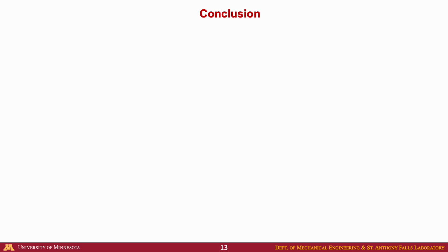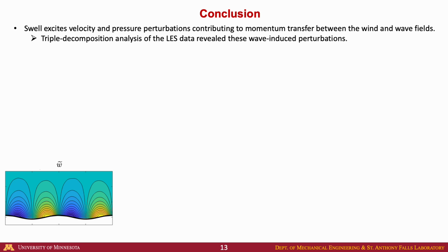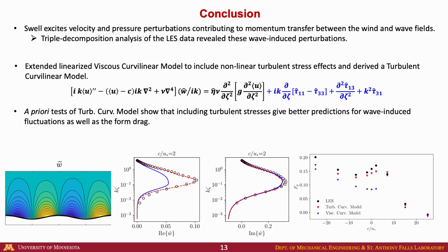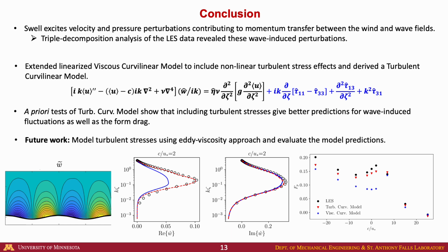In conclusion, we saw that swells excite airflow disturbances, and we were able to visualize and understand its properties through triple decomposition analysis. We derived turbulent curvilinear model equations by extending the viscous model to include turbulent stress terms. A priori tests reveal that the turbulent curvilinear model gives improved predictions of wave-induced fluctuations and form drag. The future scope of this work will focus on modeling the turbulent stress components without relying on LES data and evaluate the model predictions in a self-consistent manner.